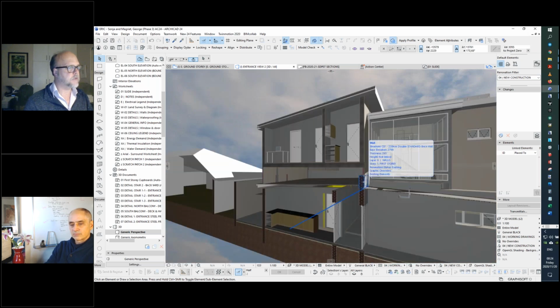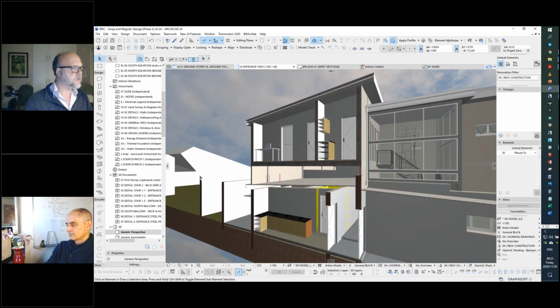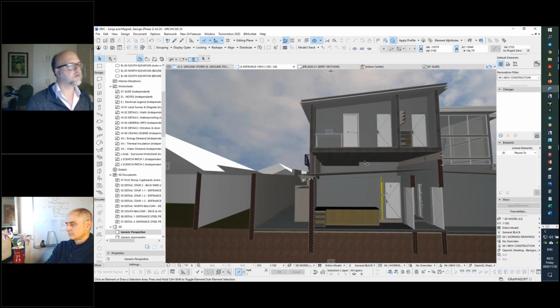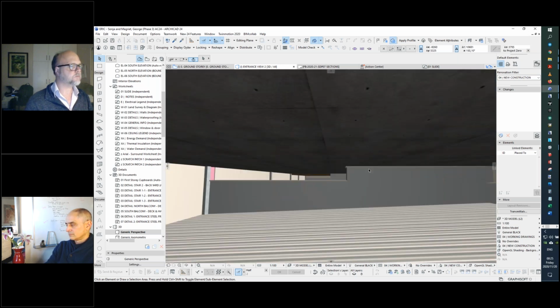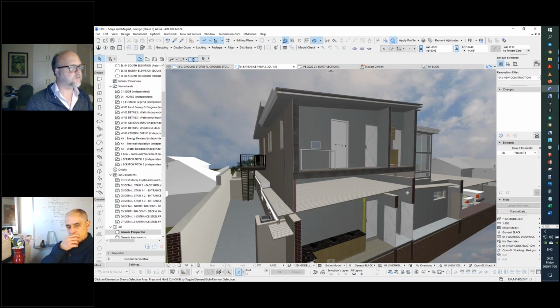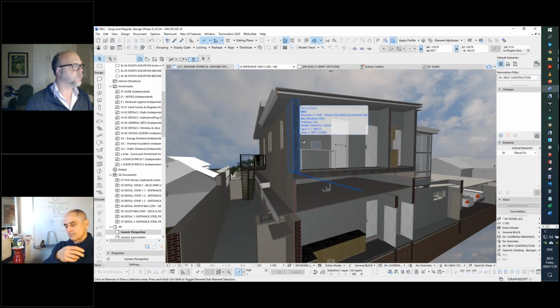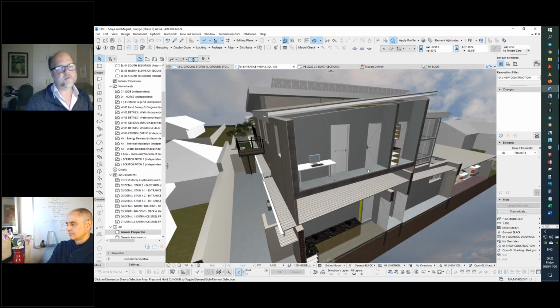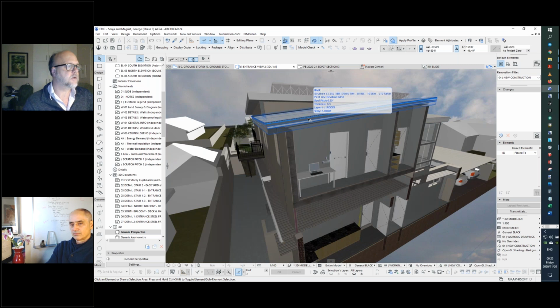So this here is the existing parapet, which we'll just build up, because these parapets are stepped, as you can see, at different levels. So we'll just have full in brickwork there to create a supporting structure for this main slab, the concrete walls, and then we're going to have structurally insulated panels for the roofing with IBR and a high density polystyrene core, structural core, and then the ceiling finish to that complete panel is then also chroma deck finish.